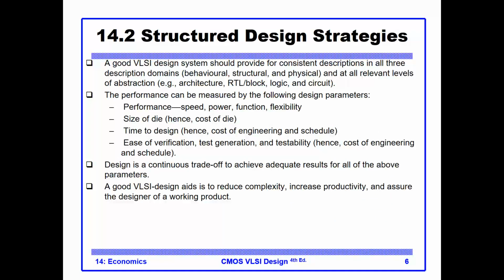Obviously, a very good VLSI design, as stated here, has to be consistent on all these views or domains. In other words, if we have something described in a behavioral level or behavioral domain or view, and then we transform this design and express it in the structural level, we better make sure that this is the same as this. If there is a mismatch, if there is a design difference, then we are not expressing the same